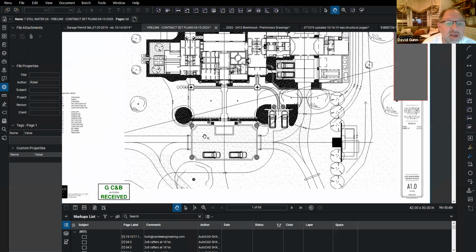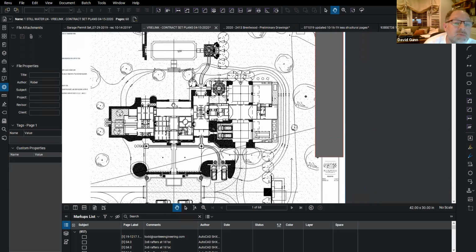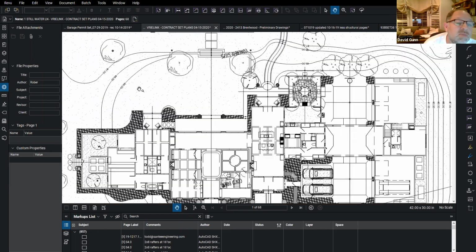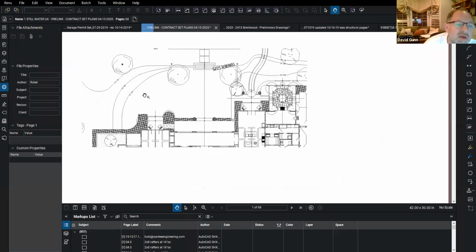If we look over here at the plan itself, this drawing, different from the first drawing, actually also shows some topography. You see some marks here. For example, that says 89, that says 88, that says 87. Those are contour lines to show that the ground is sloping down. You are 89 feet above sea level right here, stepping down to 88, stepping down to 87.